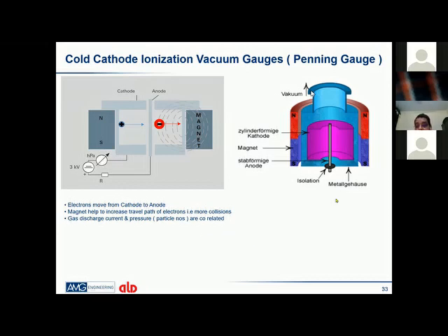We have an anode inside the gauge, and it is surrounded by a cathode. When a large electrical current is given, there is electron movement from the cathode to the anode. These are the gas particles at these vacuum levels. So the -4 and the -5, everything we are talking about is of this particle density itself. There are very few gas molecules there.